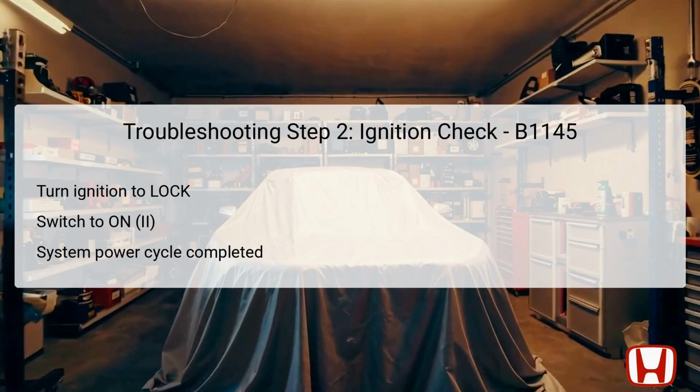The second troubleshooting step for DTC B1145 involves turning the ignition switch to the lock position and then back to the on position. This action essentially power cycles the system, resetting any ongoing processes in the vehicle's electrical system. This power cycling is significant. It ensures that the power window control unit can reinitialize itself properly and check for any lingering issues.